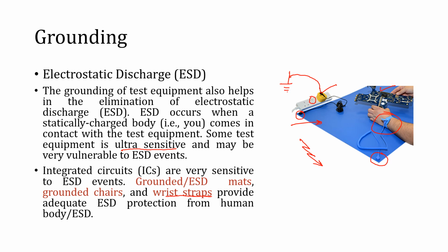So it means now our body is also properly earth grounded. So before handling such sensitive equipment, devices, sensors, transducers or ICs, we have to have these protective equipments with us. Only then can we go for the further interfacing or handling of these devices.